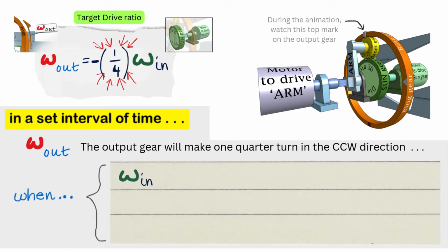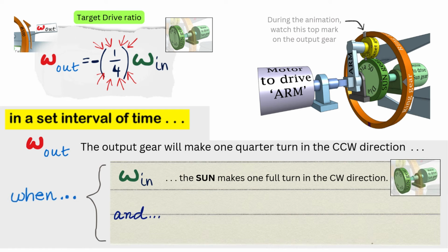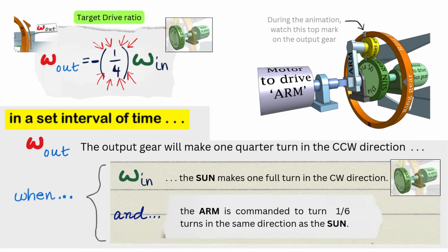So what must be blindly obvious by now is that by going from ordinary to epicyclic, we have gone from a 1 degree of freedom mechanism to a 2 degree of freedom mechanism, which is why we have the original input gear, the dia 50. It's still there. We will keep it at the same RPM. But now we have an additional input to make, which is the speed of the arm.